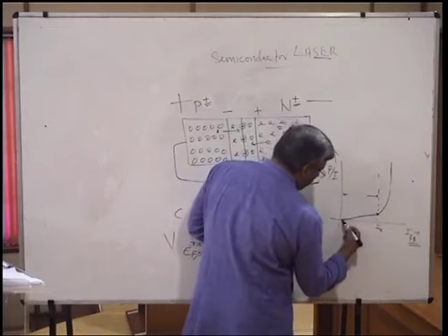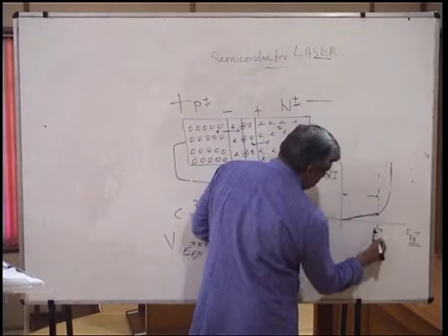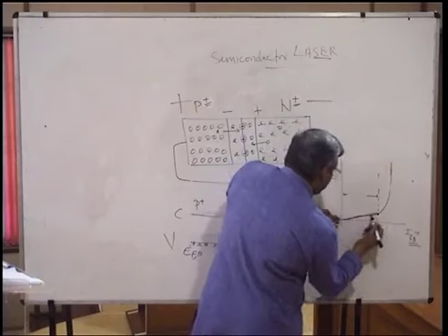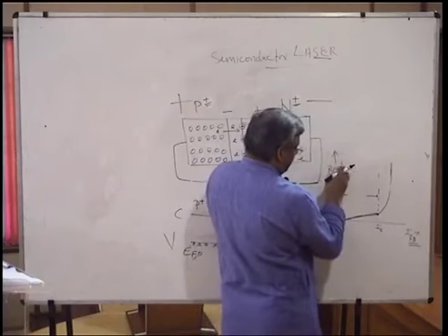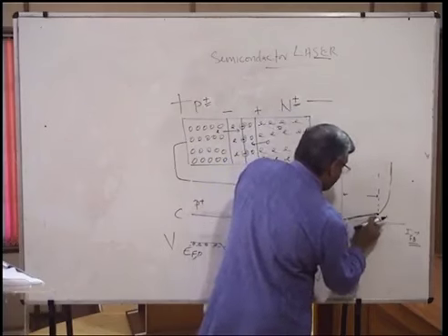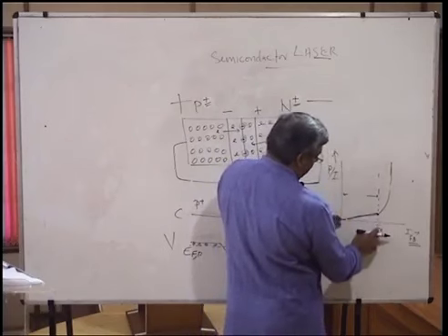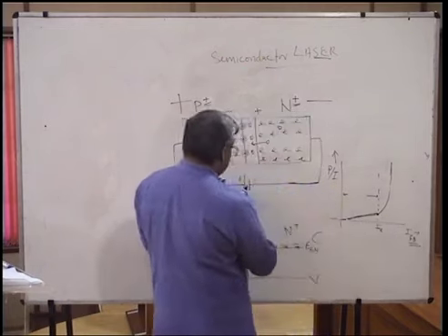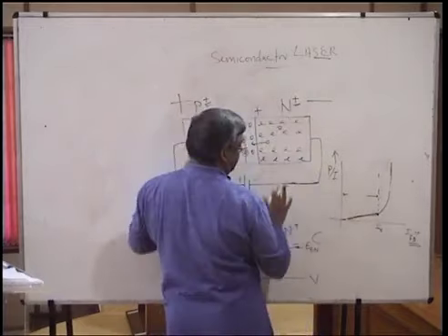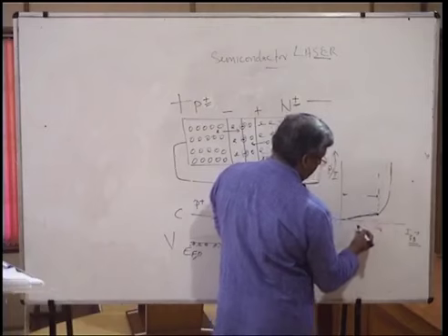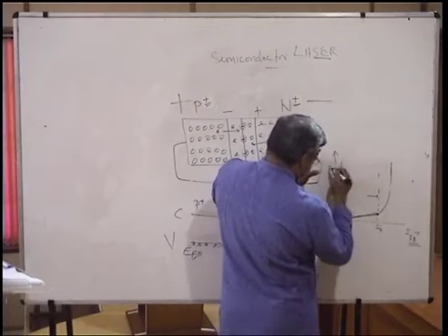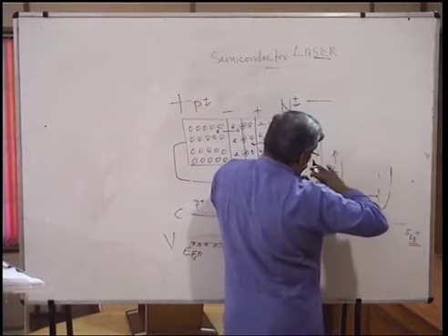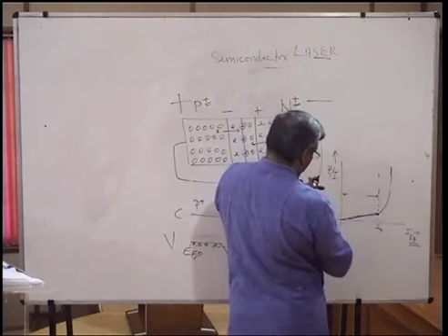Now, in this region, as you increase the forward biasing current, the brilliance of this LED will be linearly increasing. The power or intensity of light output will be linearly increasing till this critical forward biasing current. Now, if you increase the forward biasing greater than IC for a P plus N plus junction, what happens is very dramatic. This linear power increase will switch over to an exponential power increase. The brilliance will be exponentially improving and increasing.